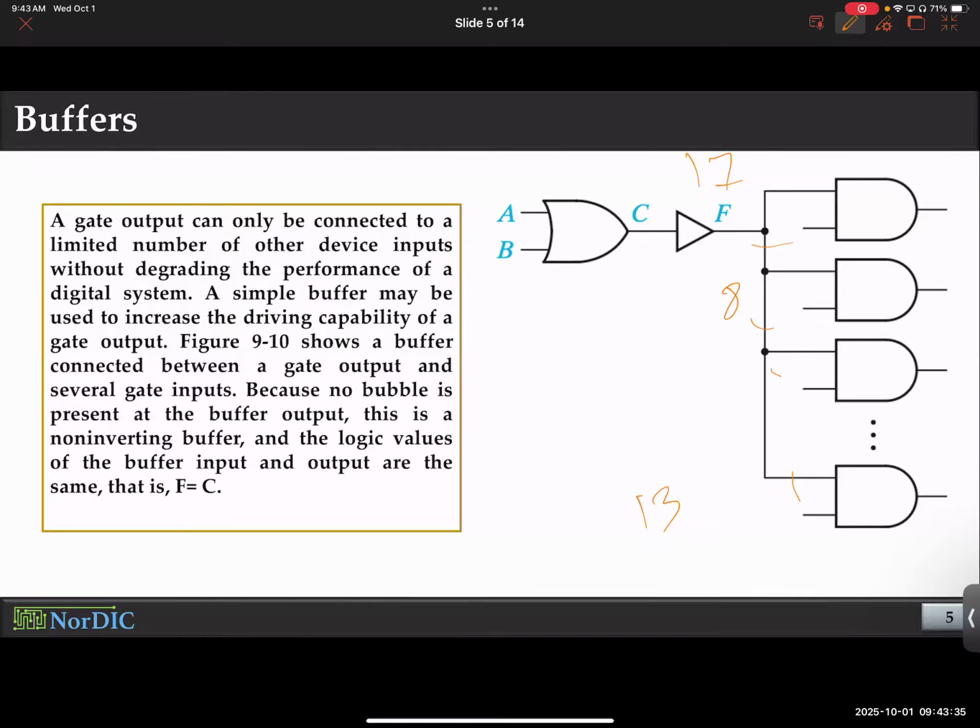Okay. So after you make all of these components, just imagine if you had to make or change their size individually, you would need an almost infinite number of components, like 50 NAND gates, 50 NOR gates, 50 XOR gates. Even then you don't cover everything. There will be situations where you say, oh, I don't have that flavor, I don't have that version, right? However, if you make a certain number of buffers, while NOR gates and NAND gates remain the same, maybe you have 1, 2, 7, 5, 3, some different sizes of the buffer. You can combine them selectively because they don't change the logic. You can always connect 1 with 7 to make 8.